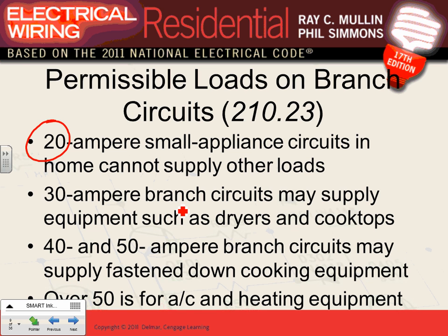Now, strongly recommended: a garbage disposal and a dishwasher, one circuit for each. If you have a sump pump, of course, it's also required to have a 20 amp circuit. What else could be a 20 amp circuit? Garage. Yes, put a circuit for the garage, recommended, not required. So these are your 20 amp circuits.